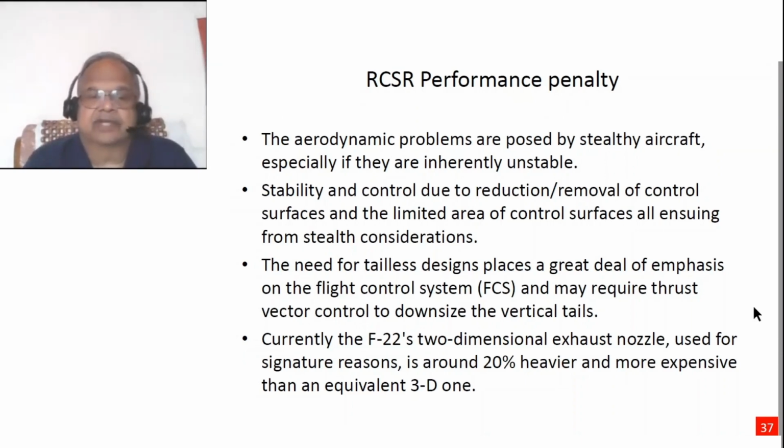F-22s currently have a two-dimensional exhaust nozzle, meaning they can only pitch up and down. They are used for signature reasons. They are, of course, 20% heavier than a more expensive equivalent 3D nozzle. So, as I said, the cost becomes an issue here too.